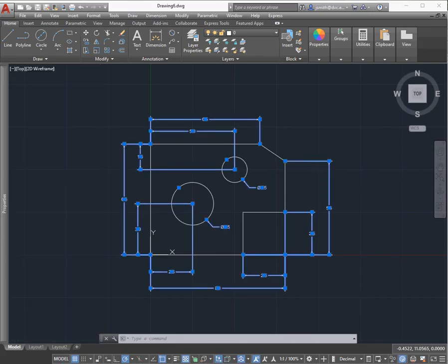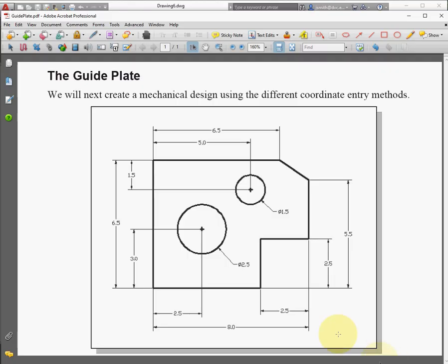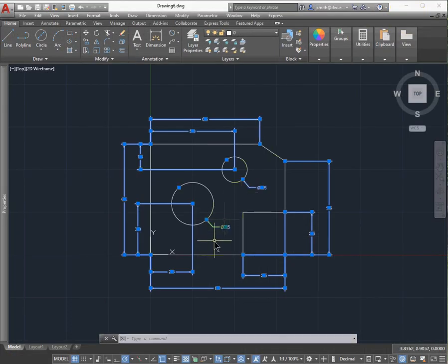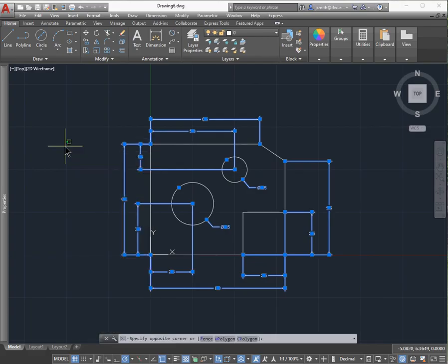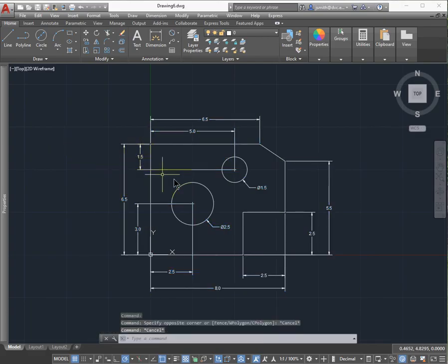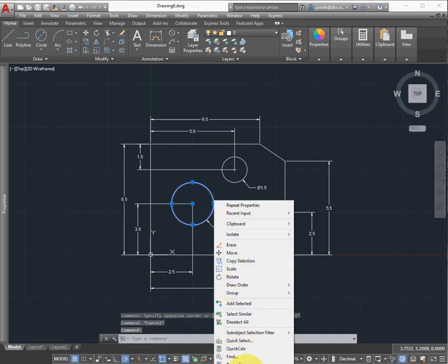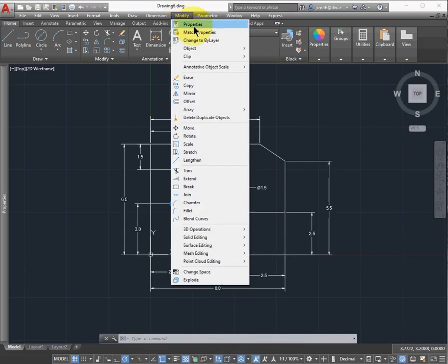And so the other thing you're going to notice is, boy, that part line is always going to be darker than the dimensions. So I'm going to go ahead and hit escape. All right. And if I hit escape, that'll kill all this right now. So you want to do that. And then what I want to do is select the line. So for example, let's go ahead and select any line, and I'll show you the same exact thing. Right click on it and hit properties, or go up to the modify on the tab and hit properties, and you're going to see something that says line weight.